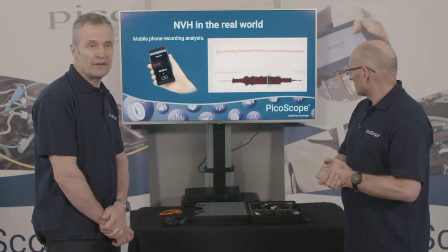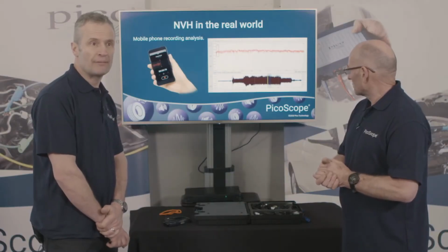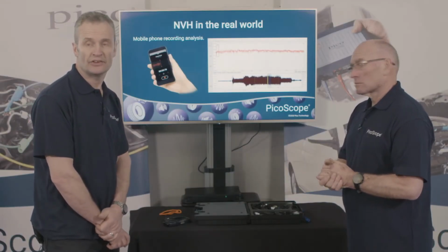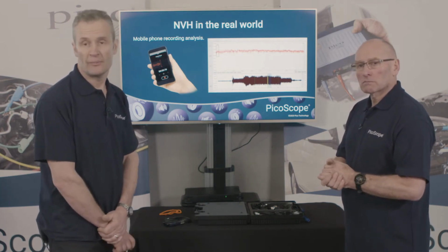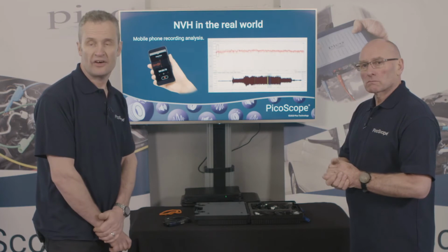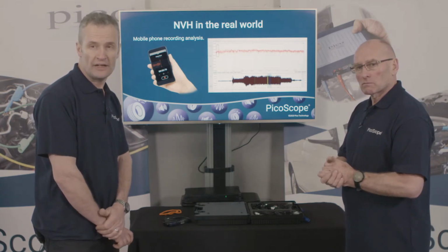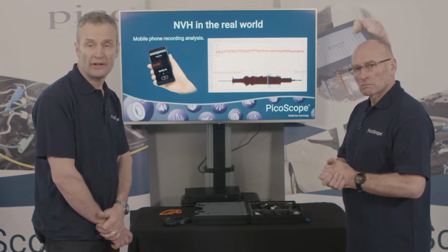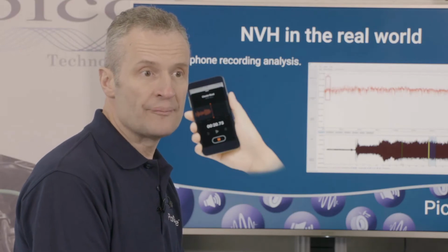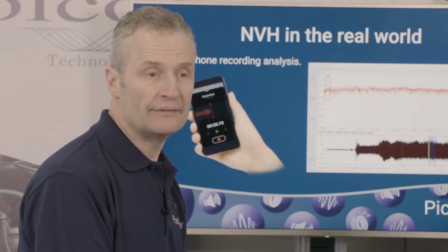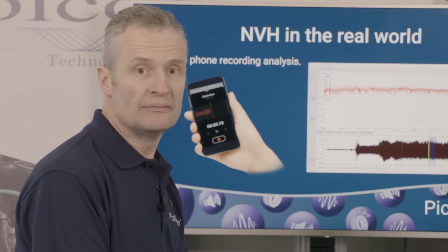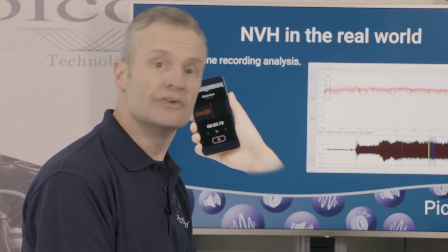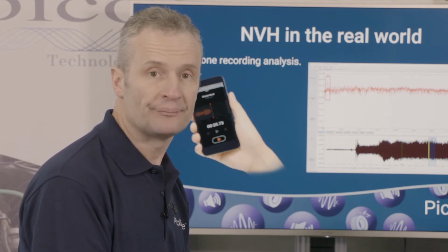If we revert back to a road speed example, if a customer came in with a recording of a noise at, let's say, 100 kilometers per hour, if we know the tyre size, we'll pretty clearly determine where T1 is and use all this product knowledge that we have in the vehicle to almost determine key amplitudes within this imported audio.